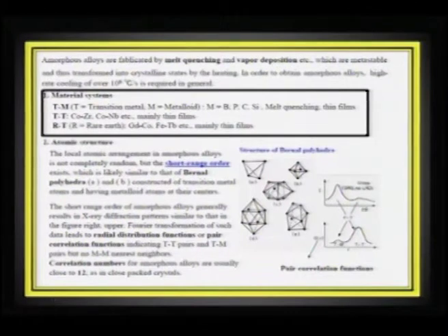And amorphous alloys are another group of compounds which show soft magnetic response, and usually amorphous alloys are fabricated by melt quenching or by vapor deposition, because you can deposit using a physical vapor deposition method at room temperature, then whatever is crystalline will actually grow as an amorphous compound, and then it is possible to characterize the magnetic behavior of an amorphous alloy. And since our course is designed more to materials chemistry, in the first module I have increasingly stressed on the use of chemical approaches to make amorphous alloys.